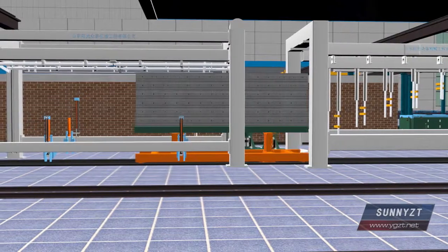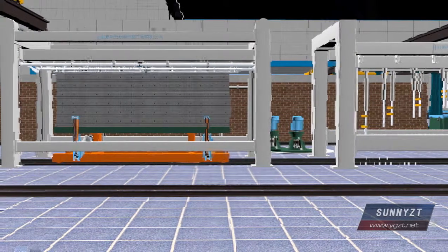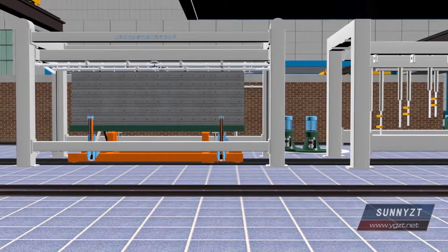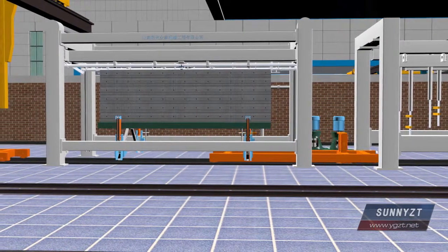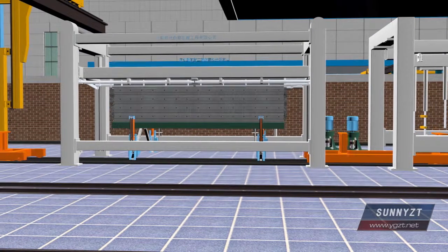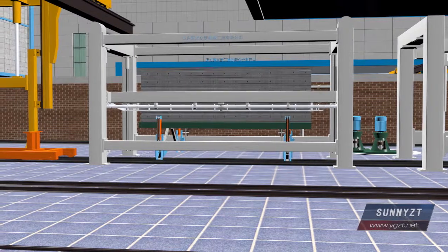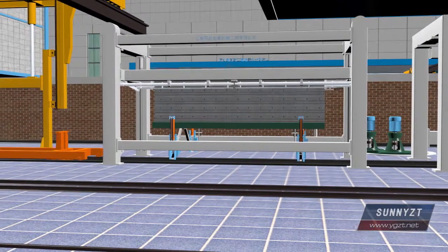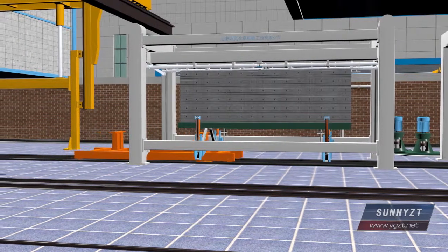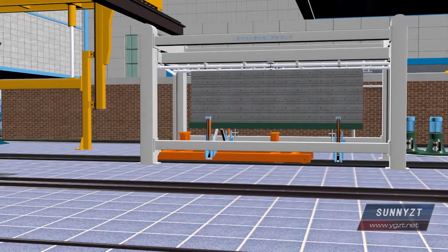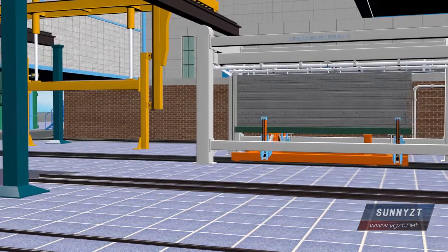After the transverse cutting, drive the first cutting trolley to the vertical cutting device. Use the hydraulic replacement device to raise the green body and the side plate. Use the four-wheel swinging cutting frame to drive the wheel wire to cut downwards. Return the first trolley to the original position to bear new green body to be cut. Drive the second cutting trolley to the vertical device to replace where the first trolley locates. The replacement device places the green body and the side plate on the second cutting trolley.